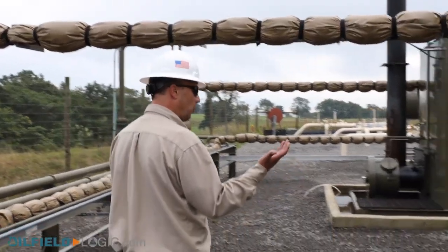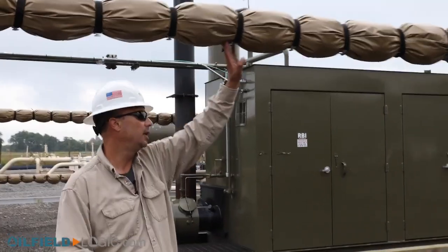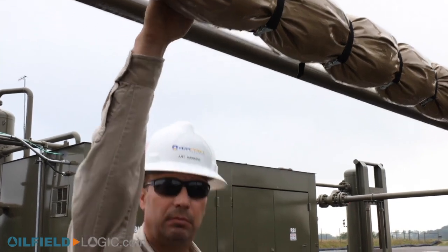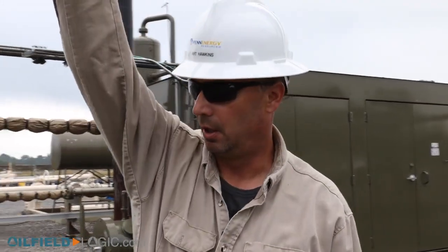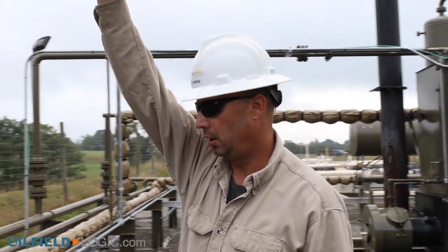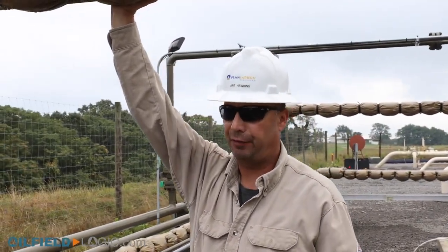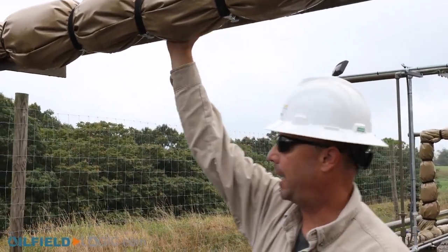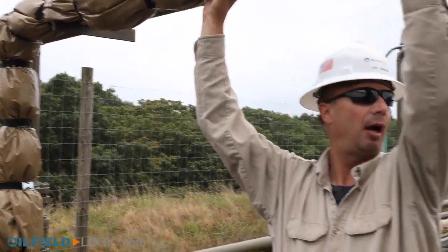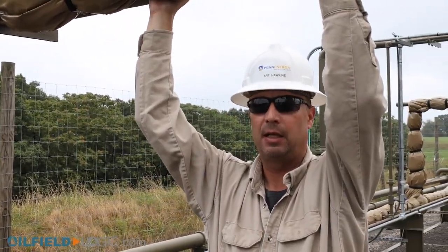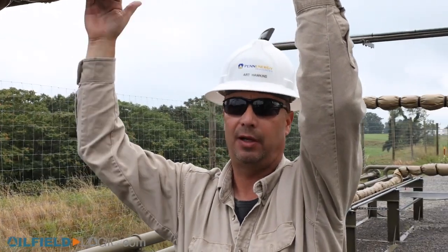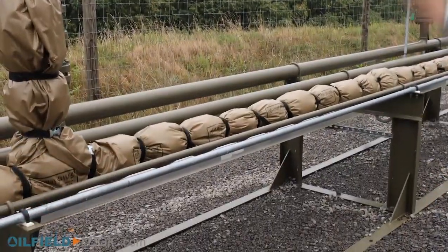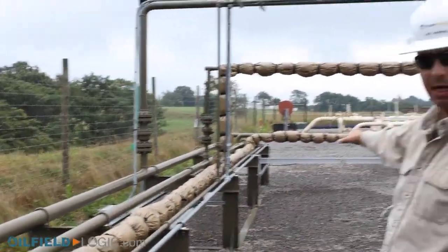Okay, and then as far as flow, like we talked about the water and the condensate, this is an insulated line that we wrap all of our condensate lines in due to temperature drops. It's normal to have cooler piping and condensate. As it flashes, it drops temperature. So to eliminate hydrate potential, we'll wrap insulation. We have heat tape wrapped around the piping and insulation to help keep that heat on the pipe and utilize it as needed. So all of our condensate will flow towards the gathering system side.